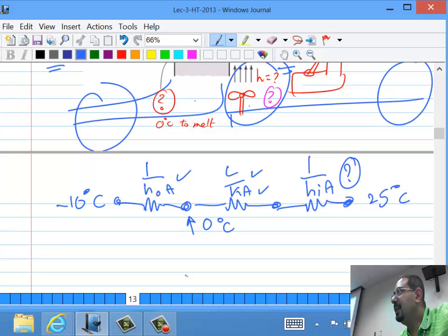We will do this in your homework that's due on Wednesday because we don't know the solution, because the wall is actually having this weird heat generation rate that doesn't make it the standard solution. But those walls are standard. It's just conduction over a plane wall. So the Q is delta T over its R, and that's it.